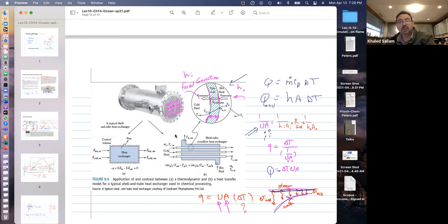That's the swimming pool if you have external forced convection. You have wind and it's flowing over the surface. Internal forced convection, that is if I would like to get this h inside, I will use the internal forced convection, right? And if I want to get the heat transfer coefficient on the outside of the pipe, because it's boiling, I will go to chapter 10, boiling and condensation, right?